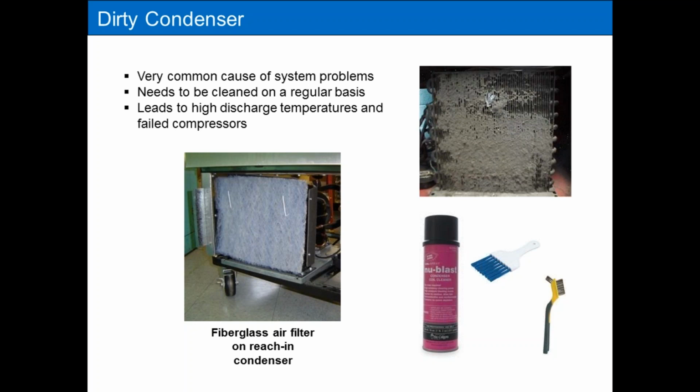There are two scenarios you're going to run across when you're looking at these condensers. One is going to be dirt, like I'm showing you on the screen here. That's going to be pretty simple for you to clean up. But sometimes in a really greasy environment, if it's in a food lineup next to a fryer, these things can get impacted with grease, and that's pretty problematic and pretty difficult to clean.